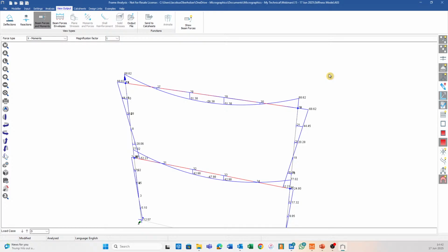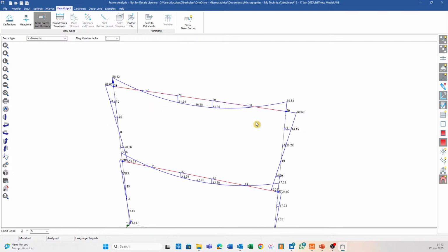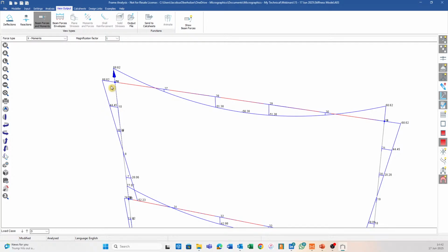You've also seen that setting something just as purely pinned or purely fixed is not really accurate to what it actually can be. And in the event that you classify a connection, you can much more accurately simulate what would really happen in the global model. However, once we start doing this in 3 dimensions and you've got maybe 4 members coming in at one point, it can get incredibly complicated.